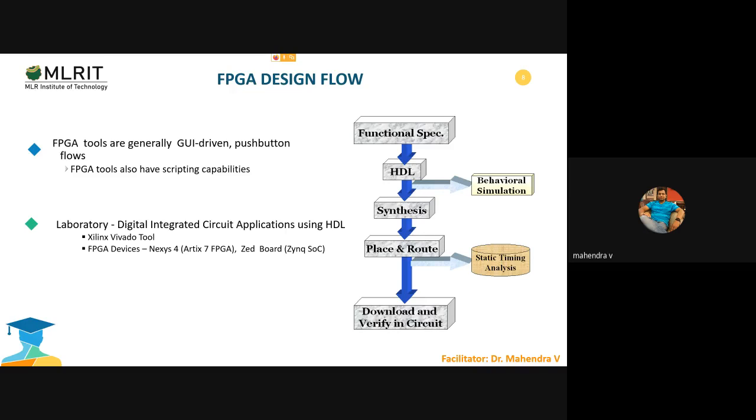Again, static timing analysis and simulation. Here the GLS will also fall. After this, the bit file will be generated, and that bit file will be downloaded onto the FPGA to verify the circuit. We can do this total process using the Xilinx Vivado tool, which is GUI driven, that is a graphical user interface, and also supports scripting languages. Here we use Vivado and FPGAs.